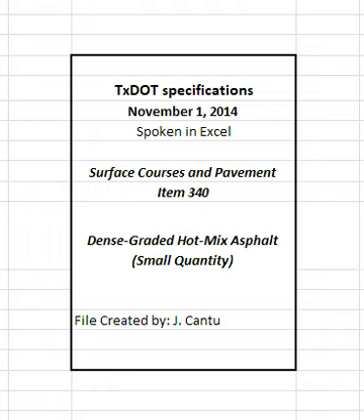1. When within these tolerances, mixture production gradations may fall outside the master grading limits. However, the percent passing the number 200 will be considered out of tolerance when outside the master grading limits. 2. Only applies to mixture produced for Lot 1 and higher. 3. Mixture is required to meet Table 8 requirements.